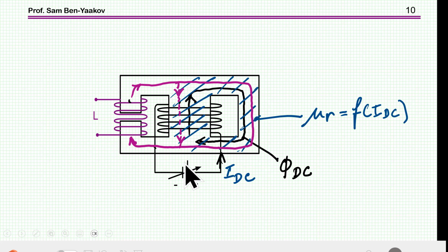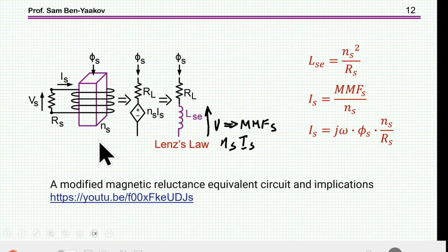On the other hand, we have here now a DC winding, and the path here now is within the ferrite itself. There is no gap here. So this portion here can be magnetized or pushed towards saturation by as low a current as we want. So we have the same feature as in the original design, but with one winding and with low AC current. So why is it that we are not going to have a high AC current?